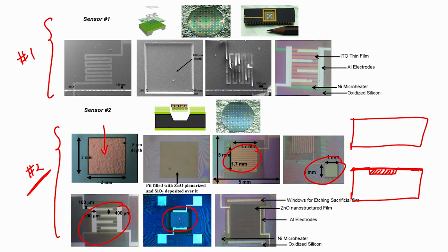Now, this is a nanostructure of zinc oxide, that is why you cannot see the interdigital electrodes below it. And then we open the windows on 4 sides and etch the zinc oxide that we deposited initially. This zinc oxide will act as a sacrificial layer, do not worry about it, we will discuss this in the class where I will be showing how to fabricate this particular sensor.